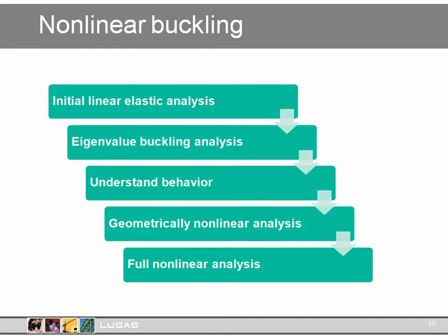We take time to ensure we understand the behaviour of the structure, partly from the eigenvalue analysis, and generally to consider if nonlinear material effects, slackening of attached cables, or lift-off, for example, might play a part in the real behaviour of the structure. We might then undertake an initial nonlinear analysis using geometrical large deformations only, before finally adding material yielding and other nonlinearities for a final solution. This process helps us gain confidence and understanding of the structural model.